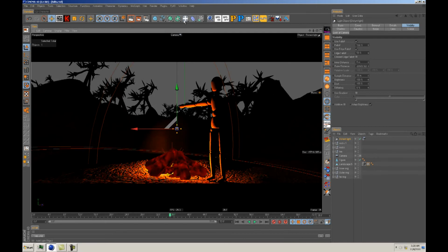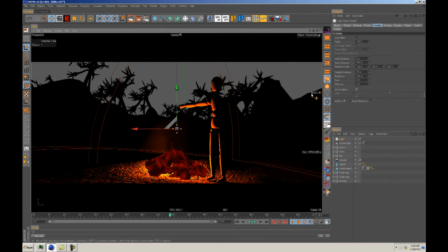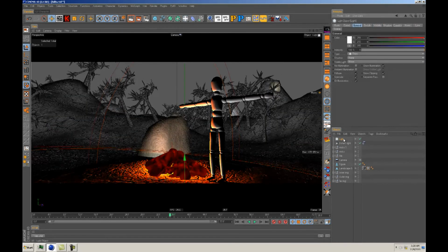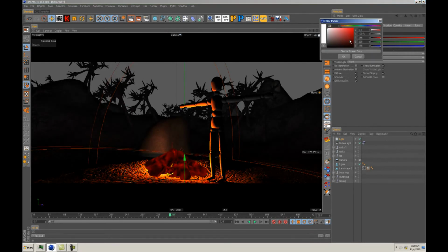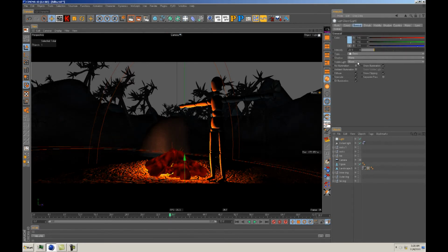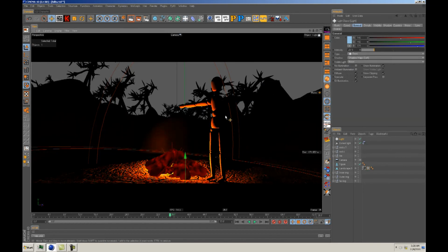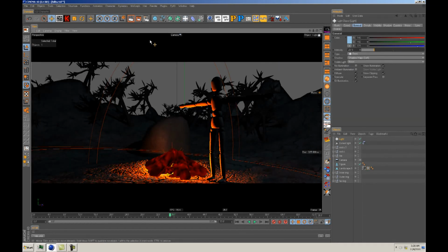So why don't we use nature's fill light and just make a moon. We're going to go the easy, cheap way and just use an omni and set it to like 20. And the moon should be some kind of bluish color, just a little bit of blue like that. We'll turn shadows on and leave them at their default, and let's just grab this and put it over here somewhere just to see how that looks.